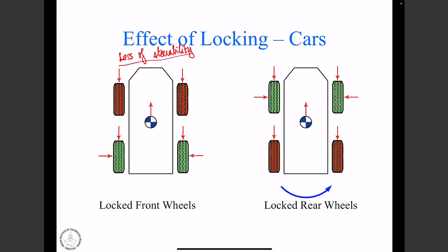Consequently, even though we may rotate the steering wheel and the front wheels will physically rotate, the heading of the vehicle will not change. I'm sure you have seen videos and photographs where the steering wheel points in one direction but the vehicle heads in another. That's because the tire-road interface has lost its ability to generate sufficient lateral forces due to wheel lock.